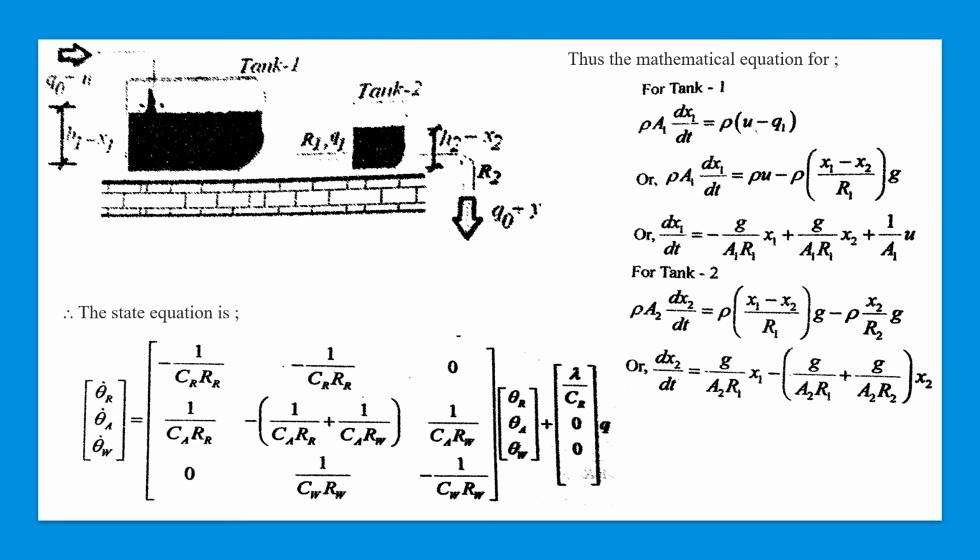Here we just assume two rectangular tanks, and the volumes of these two tanks are different. So here we can see tank 1 and tank 2, where tank 1 is bigger and tank 2 is smaller, and these two tanks are interconnected with a channel or a connector. For this case we have to derive the equation of the level for tank 1 and then for tank 2.